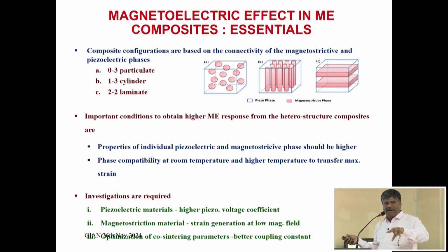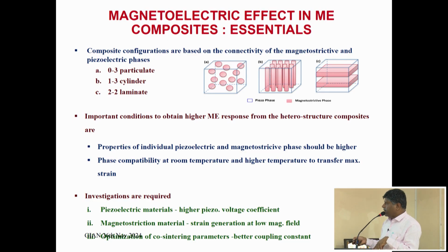So, phase A materials are well dispersed, this gives you 0-3 or 3-0 connectivity, similarly 3-1 or 3-3 connectivity, and this is a very important aspect. As I told you, if you consider piezoelectric substances like a tablet of piezoelectric substance attached to metallic substances like iron, nickel, cobalt, then those are well separated, and therefore the issue of poling does not come into the picture if you go for 2-2 kind of phase connectivity.